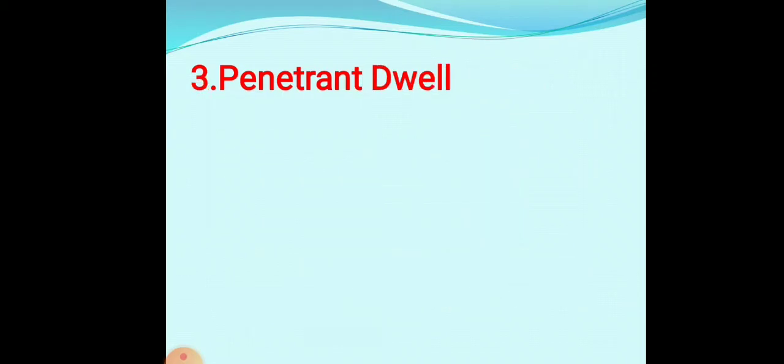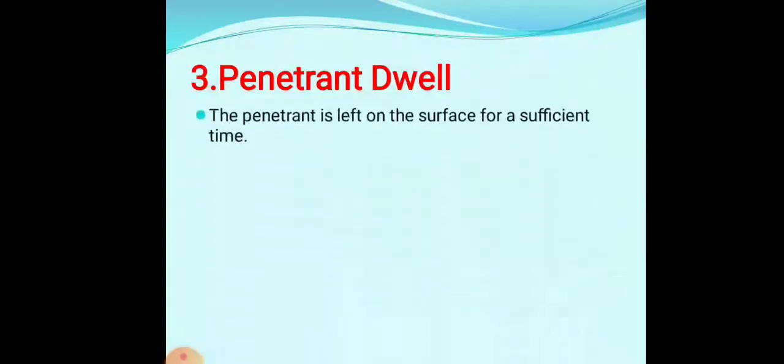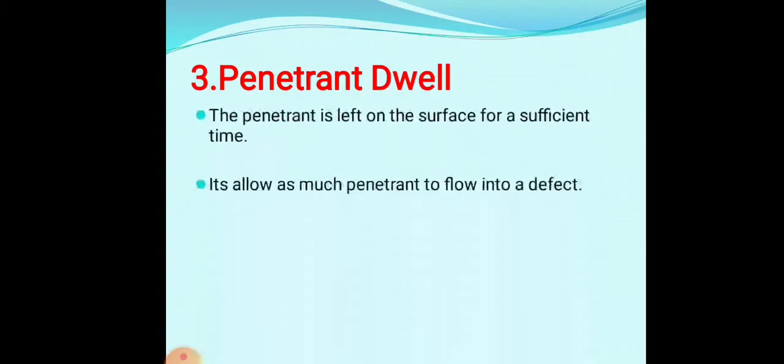Third thing is the penetrant dwell. We give some time for the penetrant to flow into the cracks. So that means penetrant dwell: the penetrant is left on the surface for sufficient time. We give sufficient time to spread the penetrant into the crack. It allows more penetrant to flow into the defect.